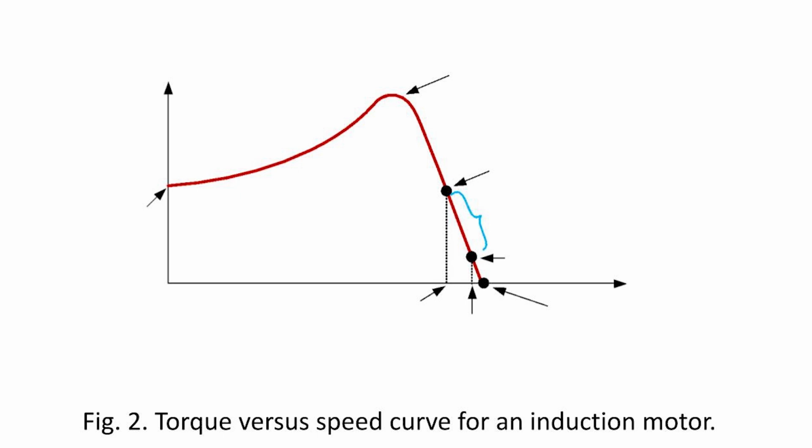As can be seen, whenever the torque increases, the slip decreases. From the curve, you can also see that there is a slip at which we have the maximum torque, which is called the breakdown torque or pull out torque. The slip at which this maximum torque is obtained can be found by differentiating the torque expression with respect to the slip and equating it to 0.